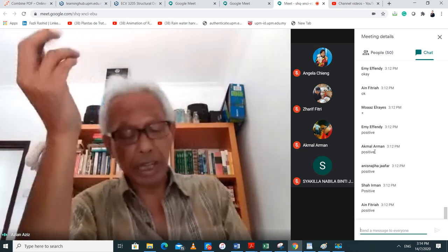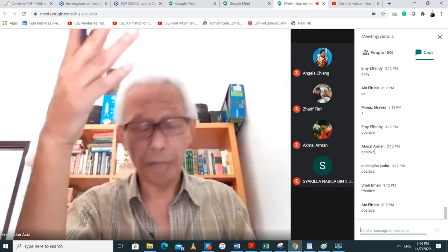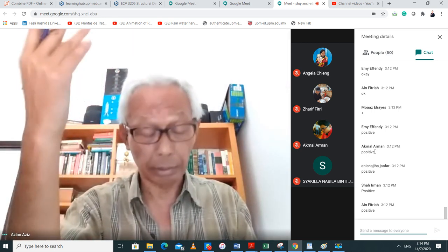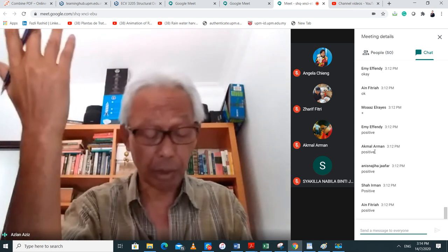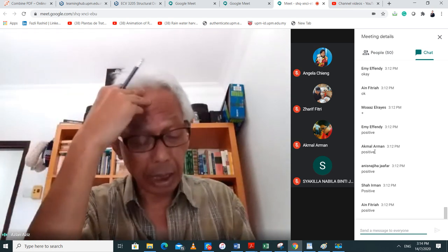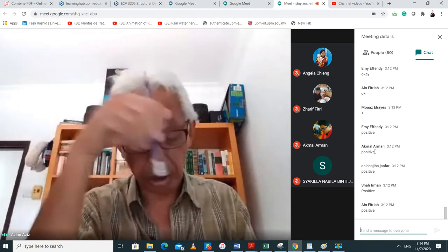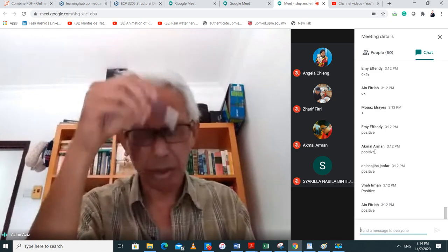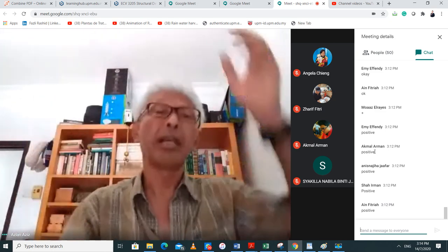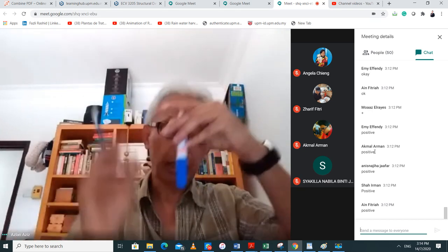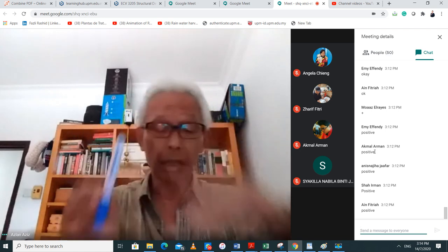Now, A sub B is 0.45 squared, given to you, 0.45 meter squared. You square the 0.45 meter, then you get the area. And A sub S is the area around the perimeter of the square. So 4 times 0.45 multiplied by the depth of the pile, the shaft friction depth of the pile.